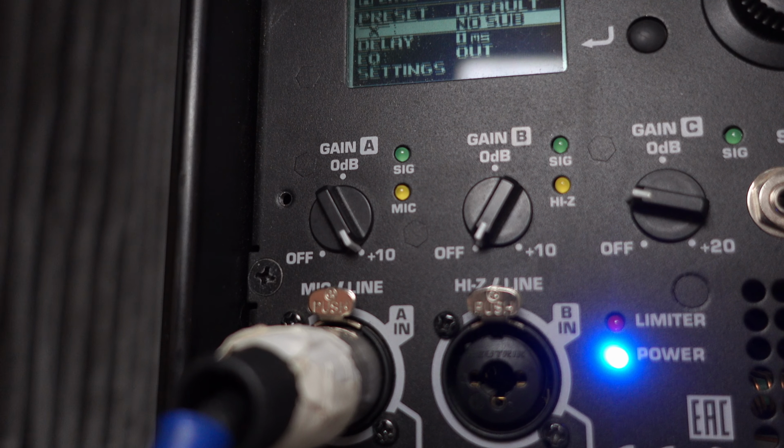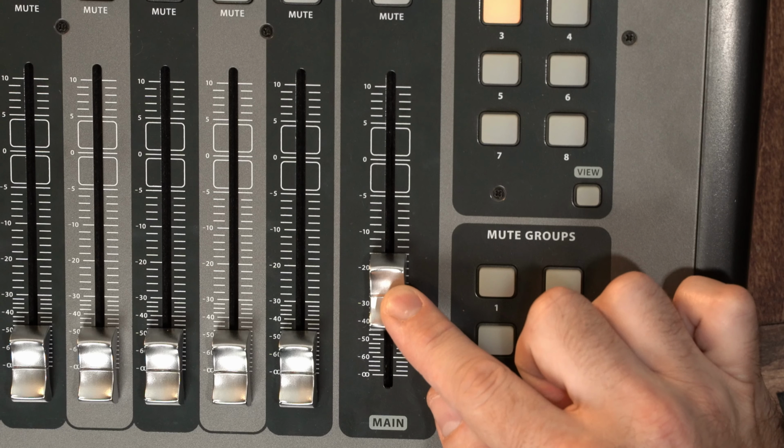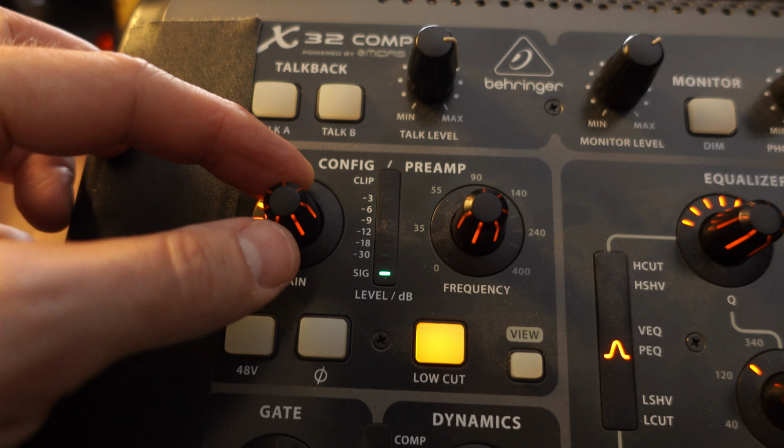Often I'll see that the engineer or the A1 turns on the speakers or amps first and sets them to some arbitrary and usually too high of a level without first running signal to them. Then they back up to the console and they put their faders at 0. Then they attempt to set input gains from that point using their ears to get enough volume out of their speakers. And yes, this does get audio out of the speakers, but it's not good audio and it's not the way to set gain.